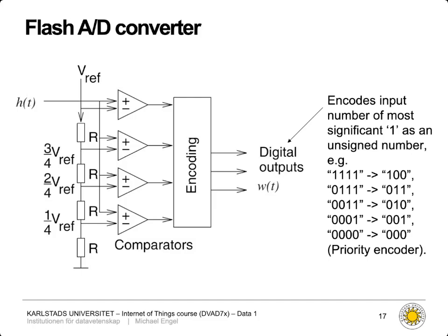So that's why when you have very fast and precise flash AD converters, these are usually in a ceramic package to better dissipate heat and are connected to very large heat sinks. For example, in high-speed cameras, things like these, where you need a lot of these things for different colors of the video signal, for example. So this can get expensive quite fast. But of course, this is a very fast converter because these comparators work almost instantly, and the encoders can also be made pretty fast.